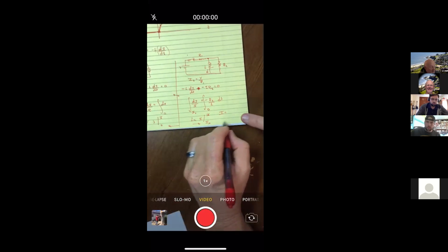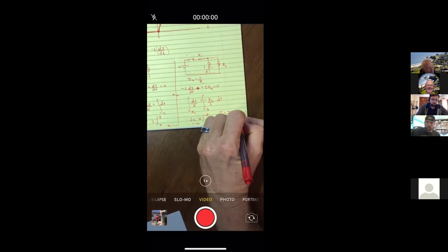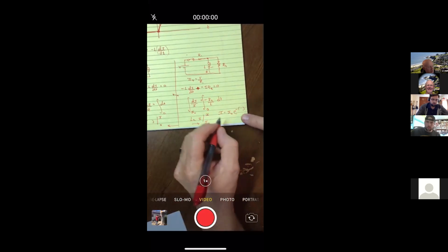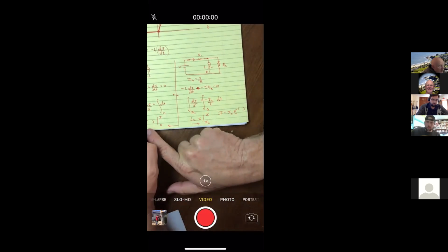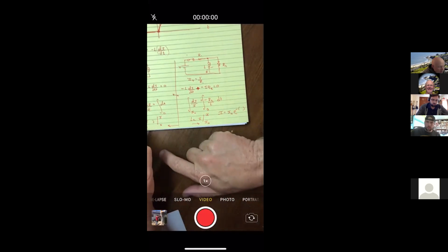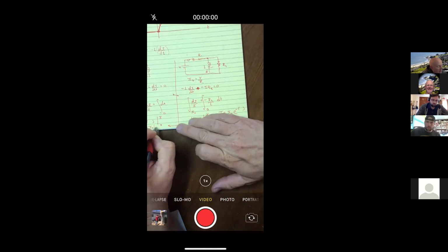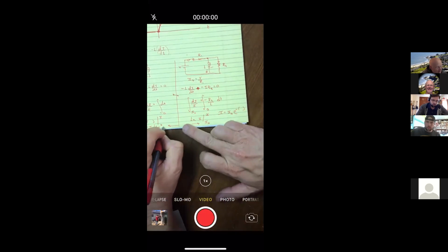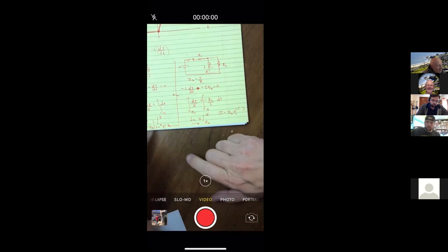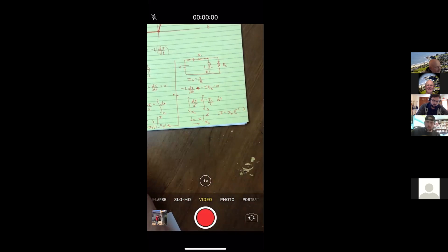Yeah, which is why then on this side of the equation, when you actually go through all the math, you get an I naught and then a decaying exponential. Whereas this one, when you go through all the math, you get I equals, and it's building up, so you get an I naught. And then as you said, you get that 1 minus the decaying exponential. But it's actually that 0 right there that makes the difference between these two.